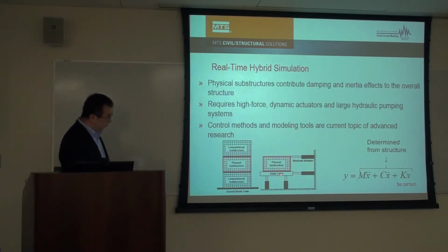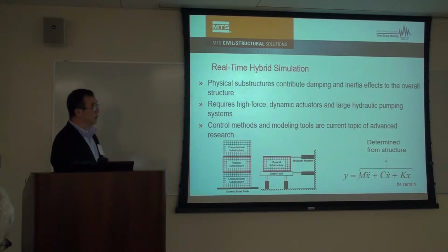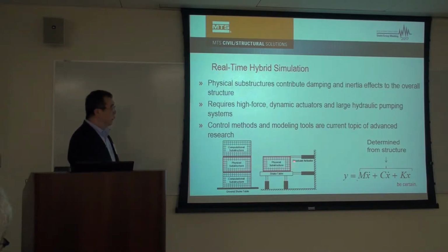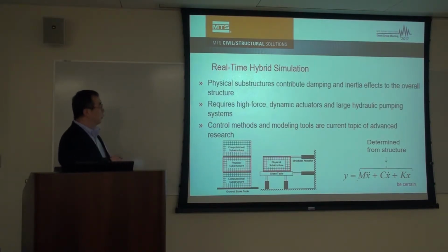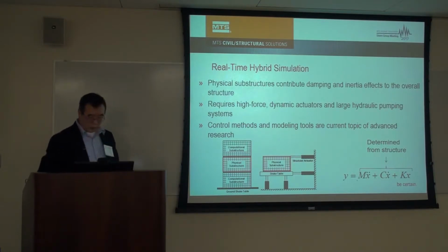The shaker table models the boundary condition of the bottom layer, and the actuator controls the top boundary. This has to be a real-time hybrid simulation because this is an inertial reactive system. So in this case, the test has to be real-time. We provide this solution as well.